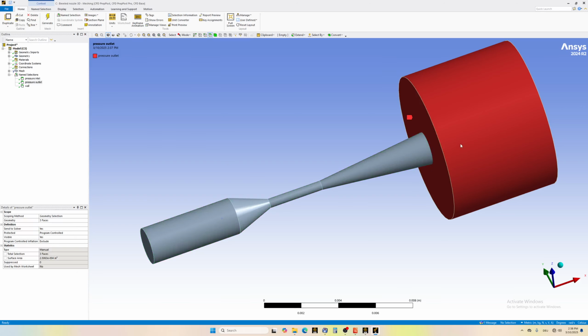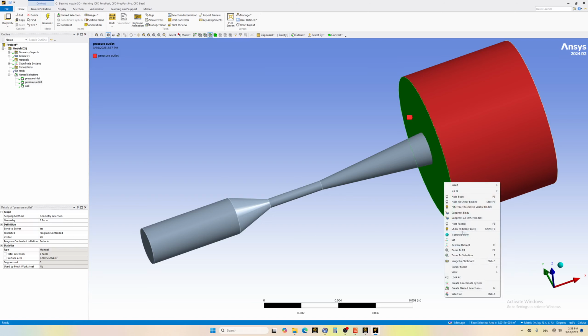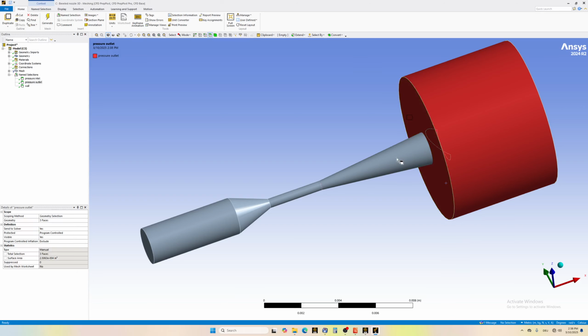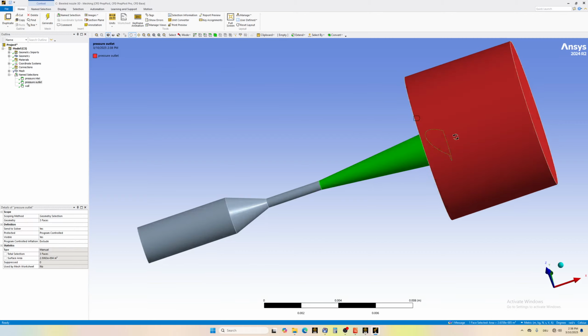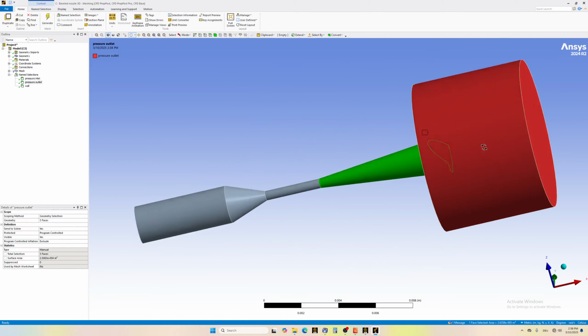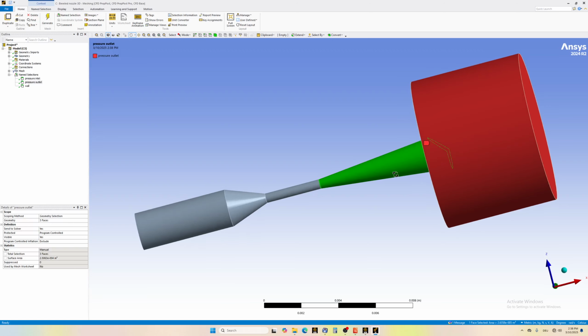So if you hide face, okay, so here is an error, it doesn't hide, but it doesn't matter, it's okay. So when I select this one, I can see the shape here. That means also the region inside is considered as wall and not ignored and considered as an interior. So we have to make sure that we have this chosen properly.